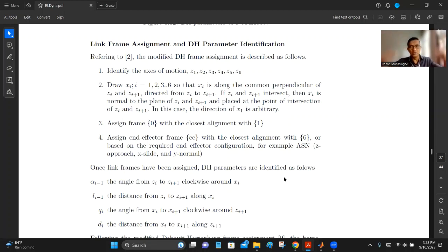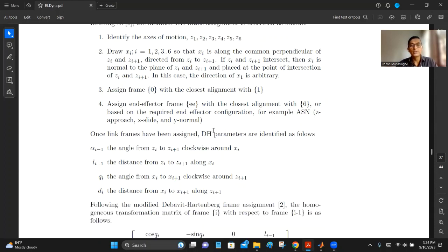You can hang it using 2 threads and swing it a bit and calculate the period of oscillation. And since you know the mass, you can measure the weight and calculate your inertia. There are various ways to do that. They did this as research and published these numbers, so we can use the same numbers for our teaching and research.